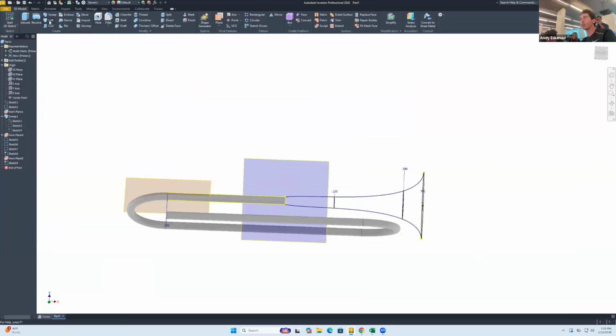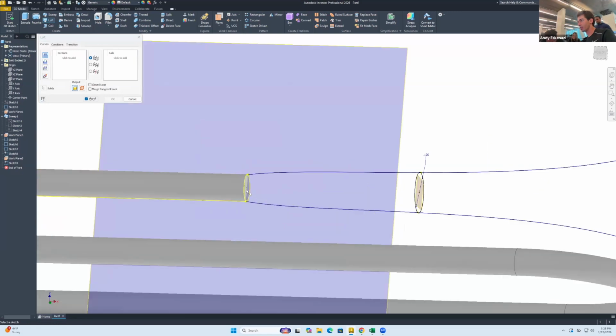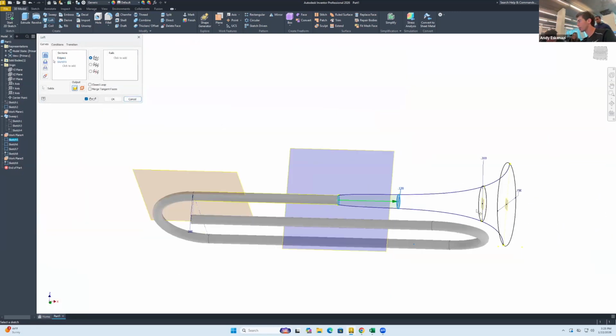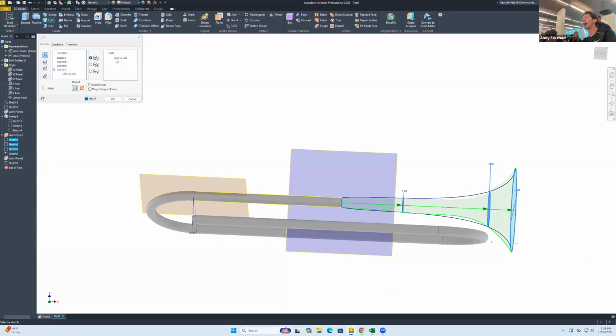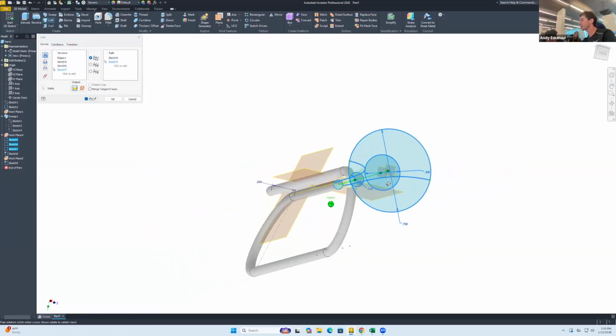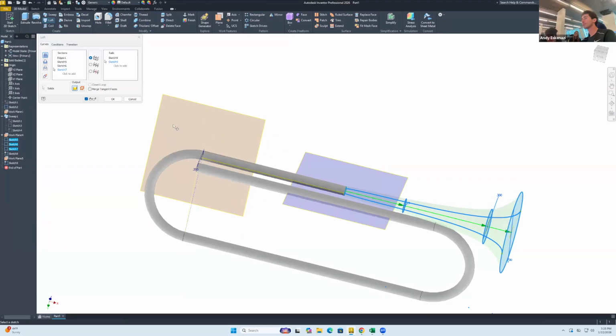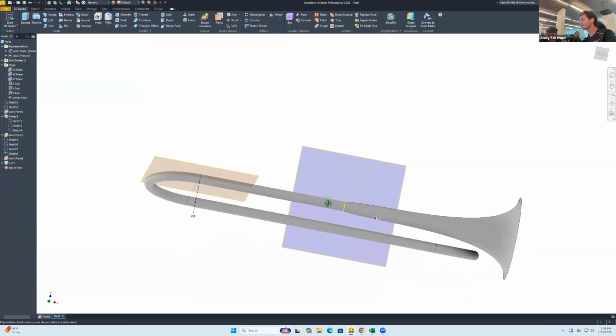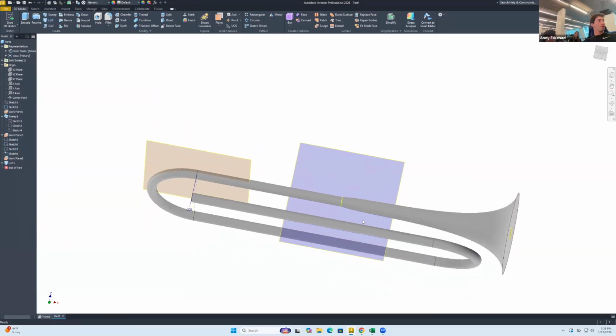But now let's try again the loft. So let's select this face, that face, that, and that. It looks ugly like last time. However, we can add rails. So let's add that and let's add that. And it looks much prettier. Okay. Ta-da! Wow. So go to this one, but not fairly difficult to do.